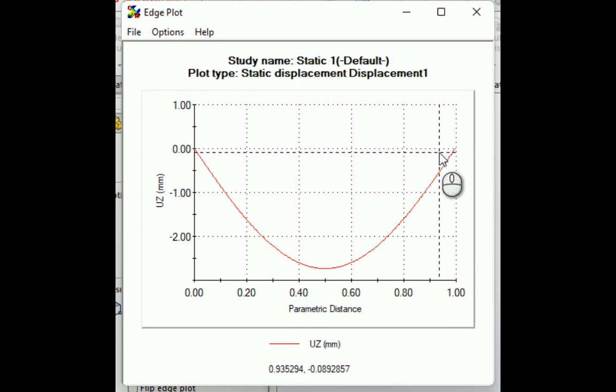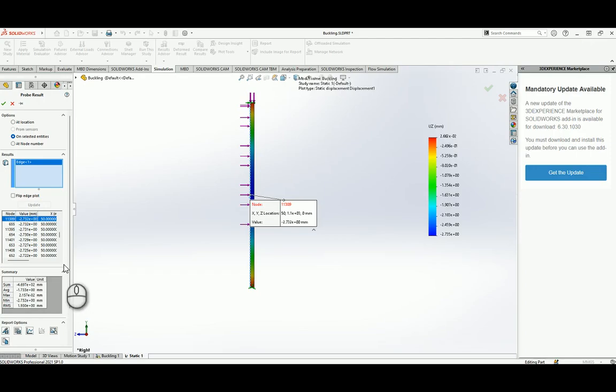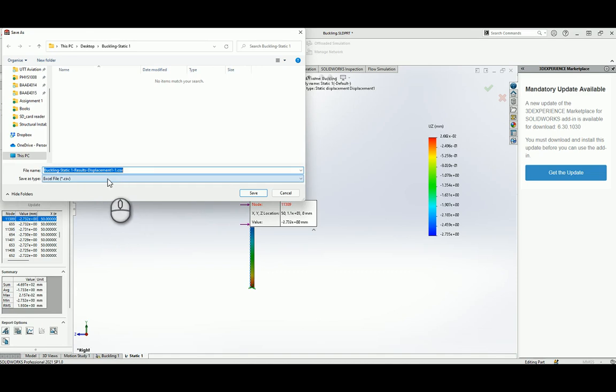Right, so this is how the plot will look. You could also export the data here to CSV files, and you could plot in Excel. You could actually plot those results from the finite element model versus the equation for V that is given in the notes on page 28. So you could plot those two graphs and compare the analytical solution versus the finite element solution. And again, that is a form of validating your finite element model.